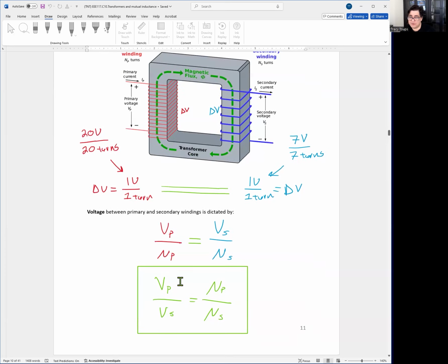Now, how can we use it for electrical circuits? Well, this ratio of primary voltage to secondary voltage, I could just say that's primary turns over secondary turns. And this is in green. This is the most key component of all transformers: you choose how much of a voltage change you want, and then you choose this ratio of turns to accommodate that. So the design side is you choose NP and NS for the customer who states, I want these two voltages. Okay.